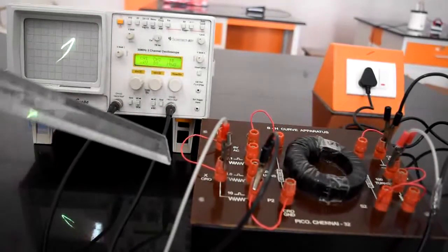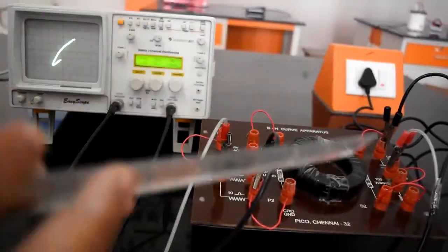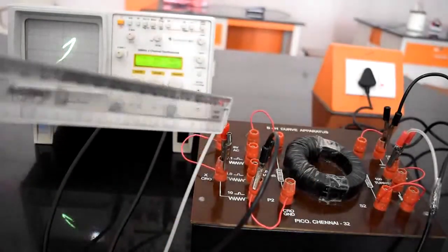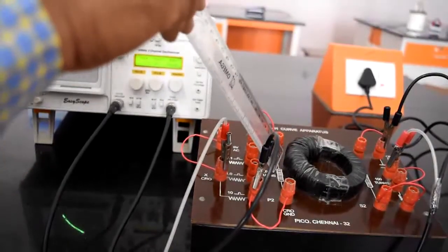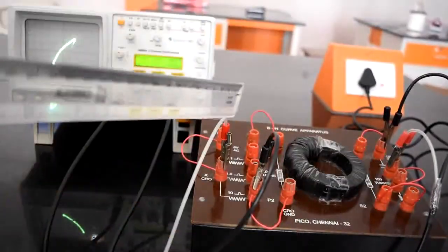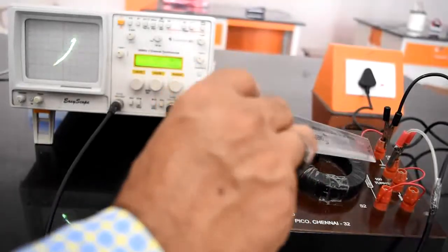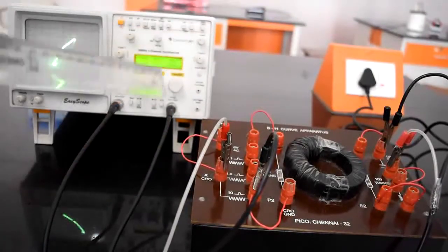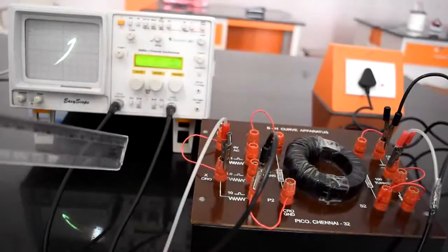And here we observe the resistances. The primary resistance R1 is 10 ohm, and the secondary resistance R2 is 680 ohm. This is mentioned here as R1 and R2. Now N1 and N2, the number of turns in the coils, are mentioned here: N1 is equal to 200, the number of turns in the secondary coil, N2, is equal to 100. Capacitance C2 is shown with the capacitor symbol, 4.7 microfarad. These are the values you notice from this circuit board. So the values we get from the circuit board are N1, N2, R1, R2 and C2.